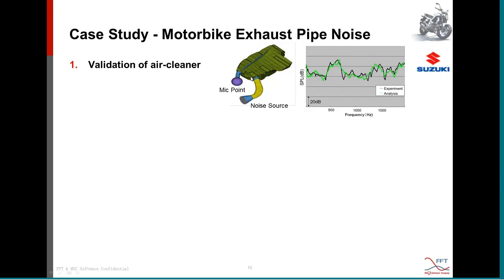We are interested in the sound pressure level at an outlet point of that air filter, and the source is a unit source applied on the inlet duct. We see that the experiment and Actran analysis give us almost perfect correlation on that air cleaner problem.